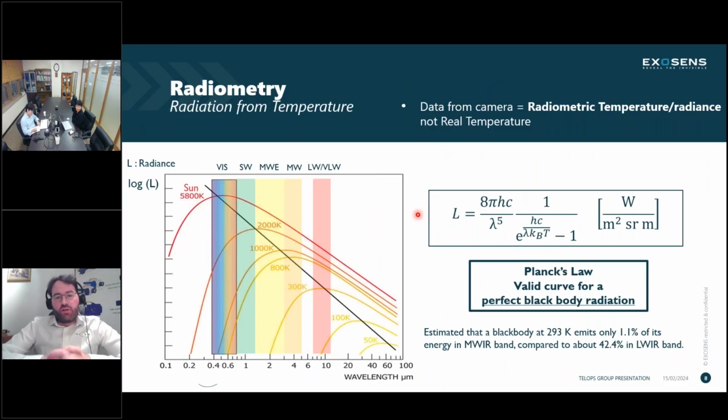So I just want to give a quick intro on what it means doing an IR measurement, what you should expect and look into when you're trying to decide the camera or IR imaging for your system. For train inspection, not everybody does IR imaging. That's the point of today, that we're trying to modernize that train inspection method. So in infrared, it's important to understand the impact of your spectral band. So you can see here in the mid-wave in this region, depending on the temperature of your scene, the peak of intensity of your signal, mid-wave compared to long wave, it's going to change quite a bit. I won't go into the details of the Planck's curve, but it's important to understand that difference in intensity of signal depending on your temperature and your spectral band.